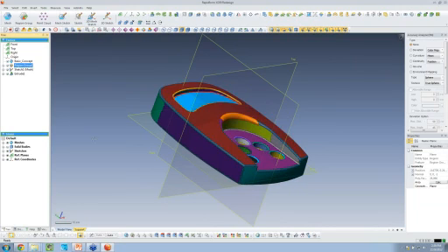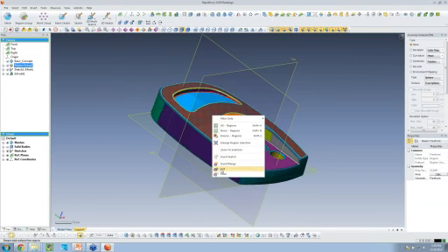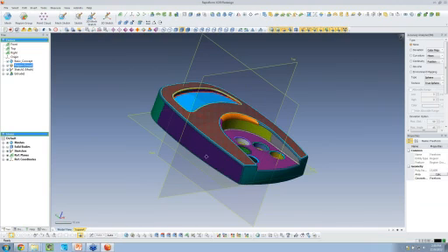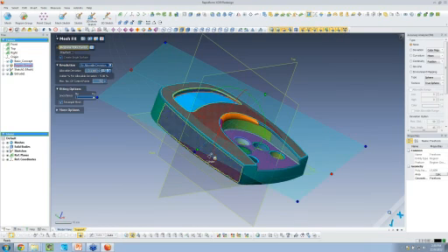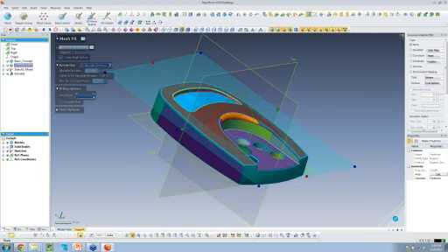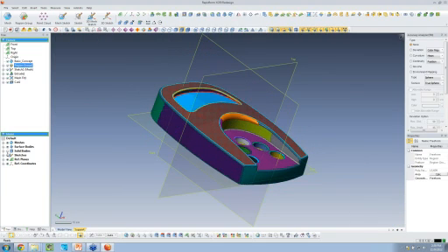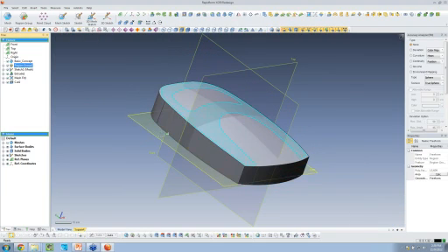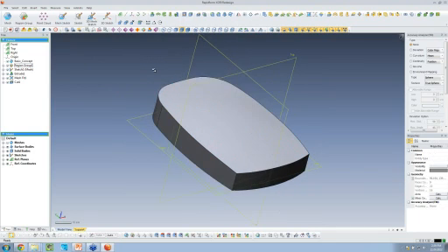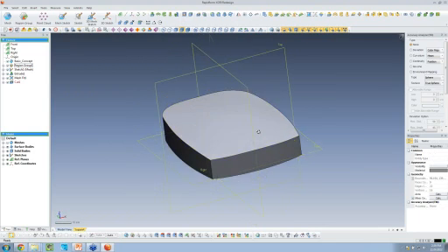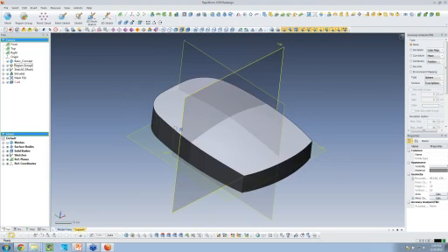Okay, very similar to that. We have the same tools available now. Once I have the feature created, I have this cut. I can cut this geometry, and I'm going to go ahead and cut this real quick. And what I'll do is I'll turn my solid body back on. You can see that I just cut that surface with that imported surface, or not imported surface, but that auto surface by right-clicking.